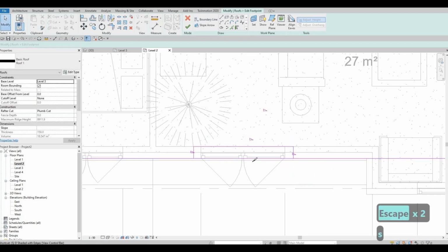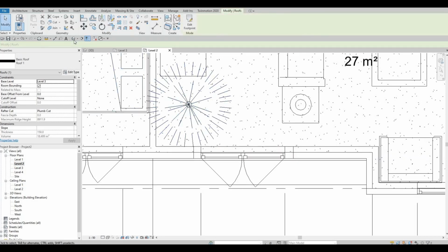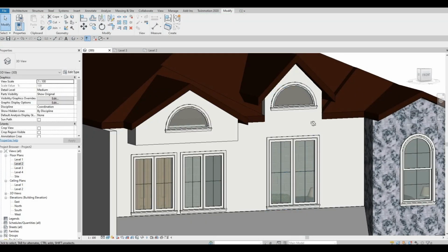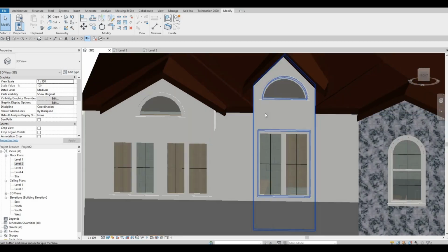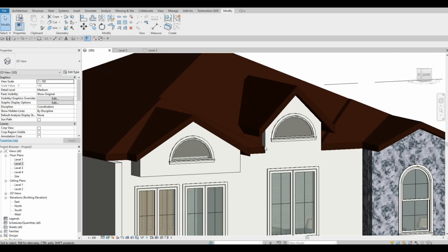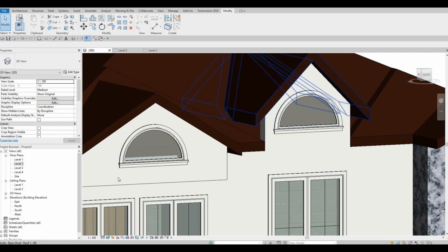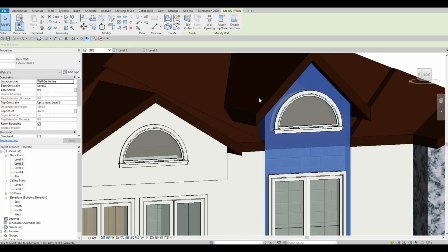And then after that, SL, that's split element, which is this icon. So TR, this is the trim command, which is this icon. So we're just gonna click it and then delete it from there. And then after that, as you can see, we have room for here now. After this, we need to add in backings there. So we need to add the same wall, not an extrusion.